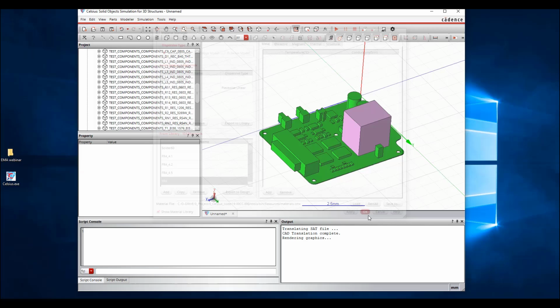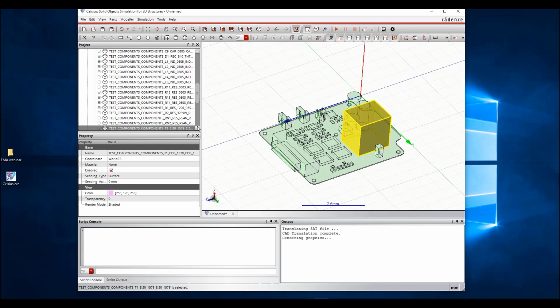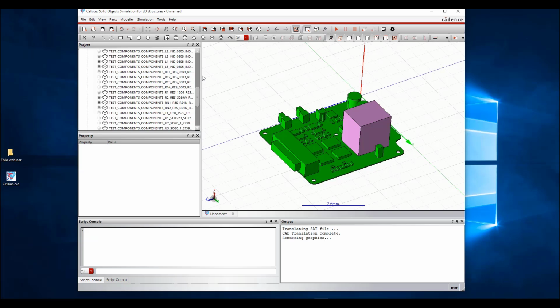Then I click OK. Then I click this component. I could choose material from the list I have built. So the user has to specify material properties. Then we are going to implement an automated process from the output of Allegro. Say this is a SAT file. SAT file doesn't include any material properties, so we may be able to create another file like a text file. Then we can import it together with the SAT file. Then all the material properties are already assigned there.